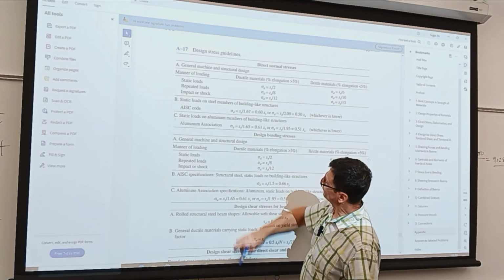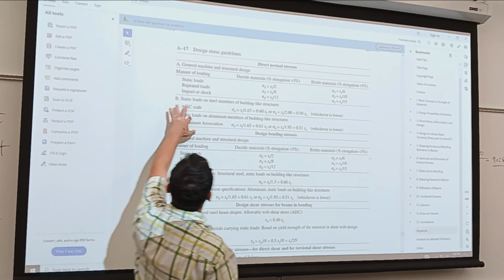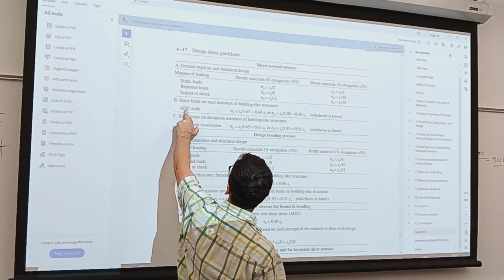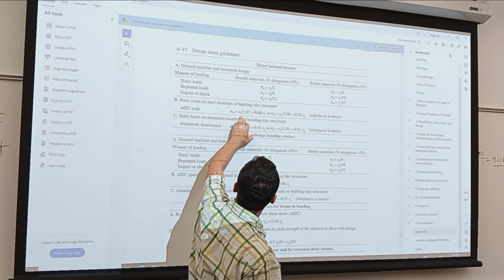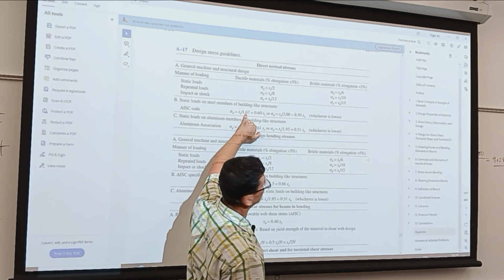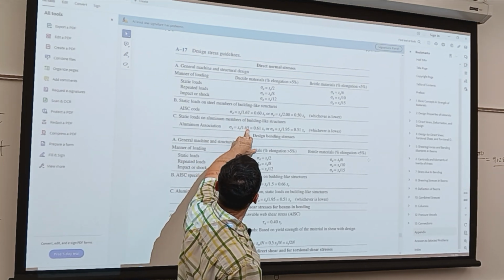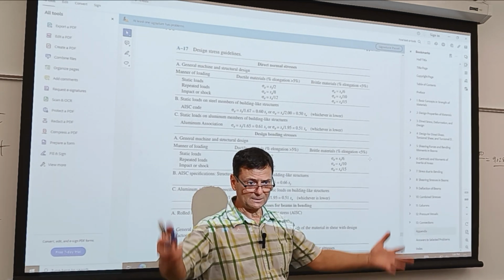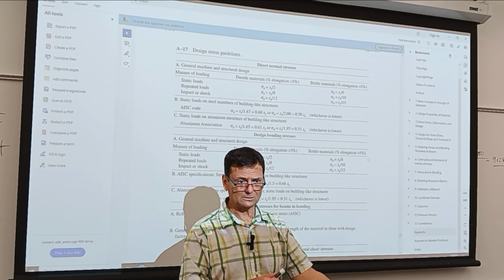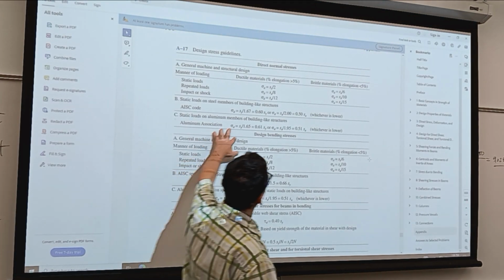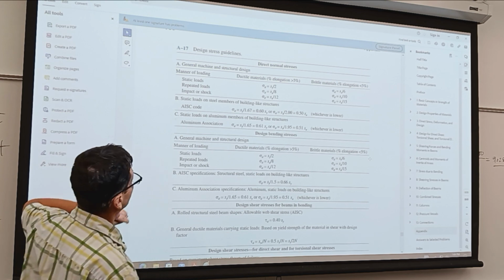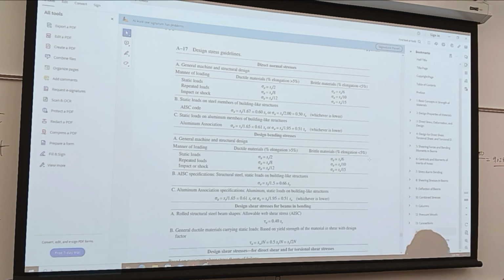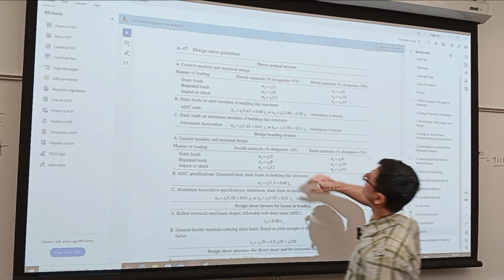And this is where we find, so there's more to it, like it says for building light structures, design stress, American Institute of Steel Construction, design stress, yield strength divided by, so this will be a design factor. You can see it's less than 2, 1.67. If you work with aluminum, 1.65, but these building light structures assume one-time loading. That's the dead load, and then occupants, their additional load is assumed negligible. Bridges is different. For bridges, this is meant for the civil engineering majors. You'll learn more in the structural class.